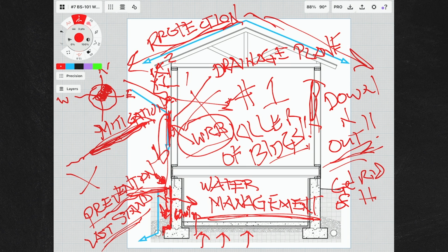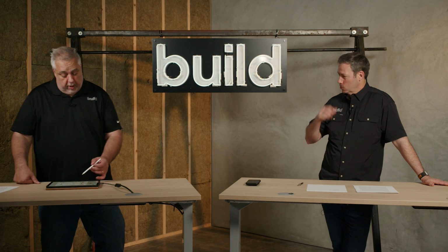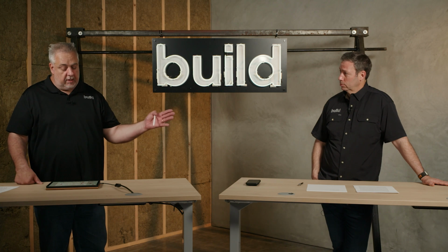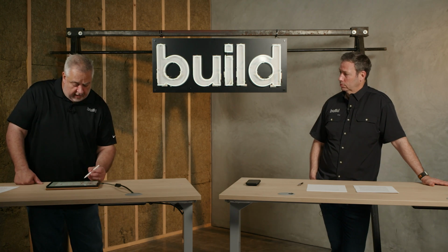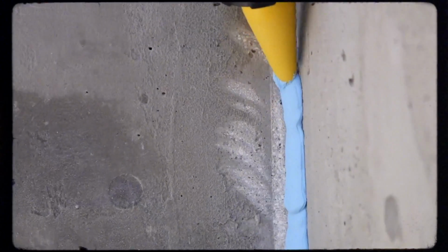And the waterproofing doesn't stop necessarily at the bottom. You want to take it over the footing because there's a cold joint down here. Yeah, that's right. And I have seen projects where water has come in through there. For the cold joint, a lot of people will put a capillary break on top of that. There's some stuff that you can trowel on. There's membrane type systems that you can put on there. I think there's a manufacturer that makes a caulking that they can put in there.